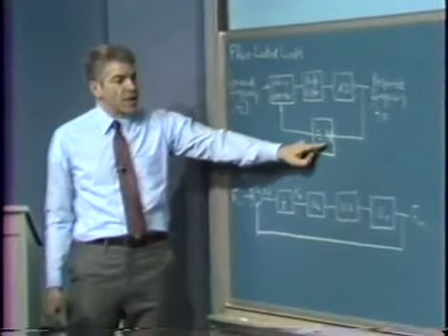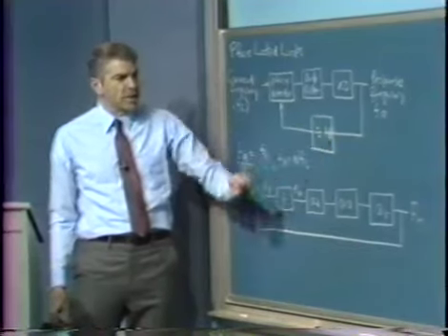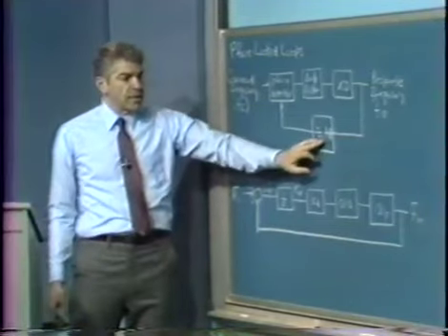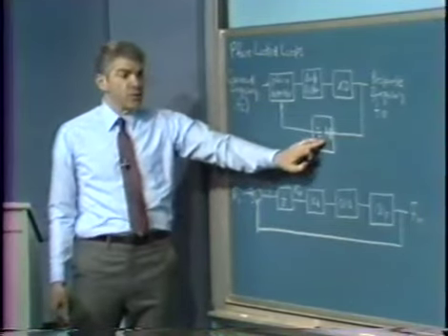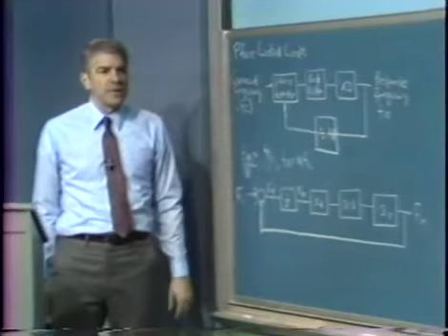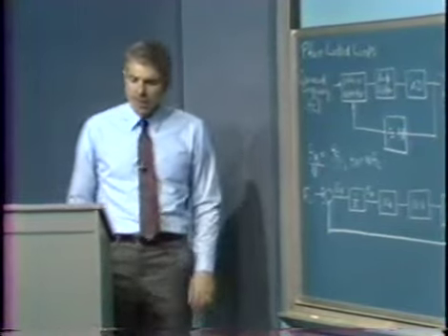That problem exists, for example, oftentimes in the frequency synthesizer. You make a step change in N, change the value of N, that disturbs the loop, but in many cases you'd like to have very rapid settling to a new frequency at the output. That kind of rapid settling is a very challenging sort of design problem.